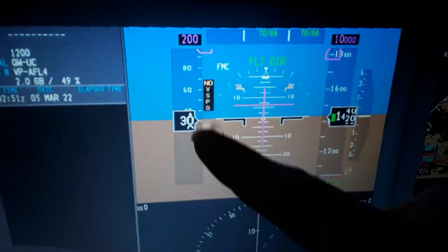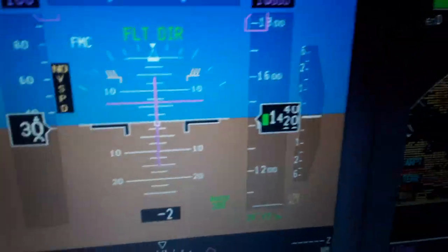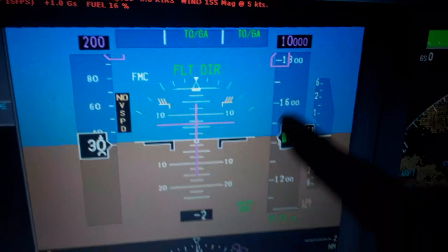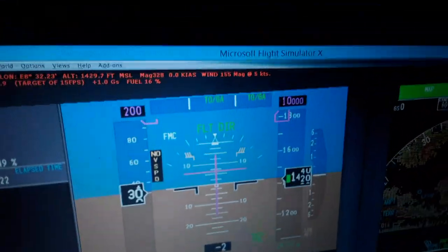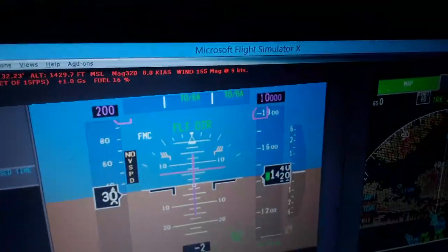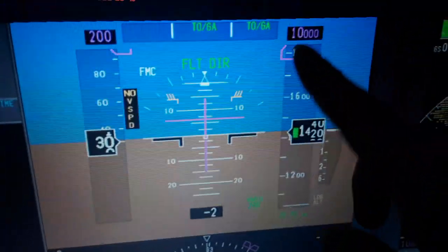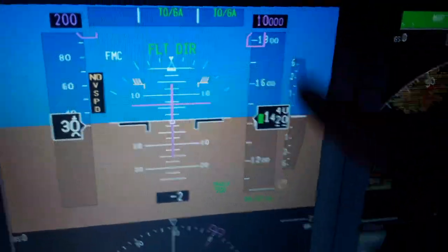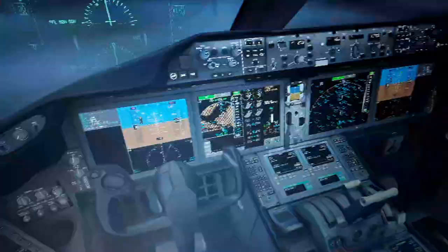The actual airspeed right now is 0. We have the radio altitude above ground level, the barometric altitude above sea level, the target altitude selected from the autopilot flight director system panel, and the vertical rate of climb or descent of the aircraft in tens, hundreds and thousands of feet per minute.